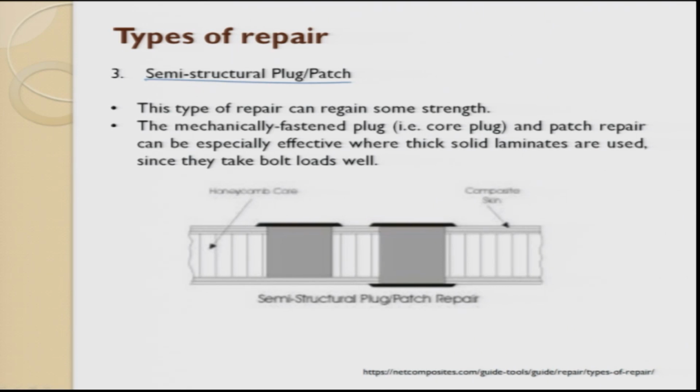This type of repair can regain some amount of strength. Mechanical fastening plugs, a core plug or a patch repair can especially be used where thick solid laminates are used, since they take bolt load as well.